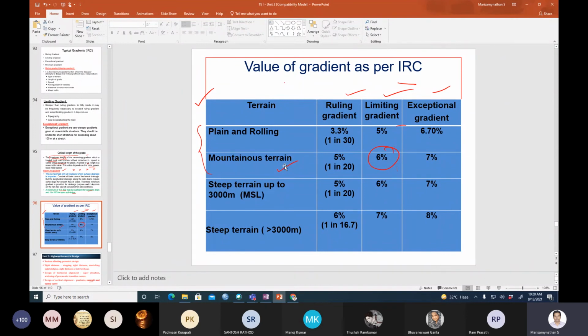Questions might be expected on this. It is simple and straightforward, but it takes a lengthy procedure. They won't give the extra widening or the super elevation. In that case, you have to estimate the super elevation as well as the extra widening, and then apply them in the equations. Finally, for the three cases, whichever is the maximum can be finalized as the length of the transition curve. Sometimes problems ask for the shift, and based on the maximum value, speed and radius, you have to estimate the shift value. This is what we have covered.